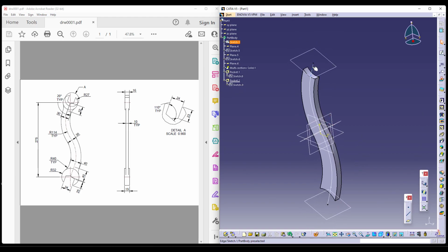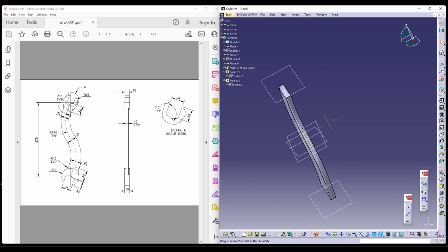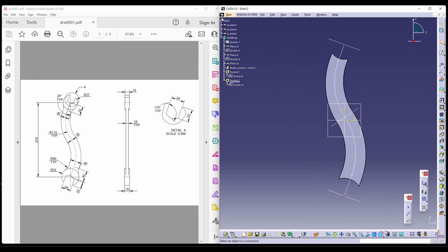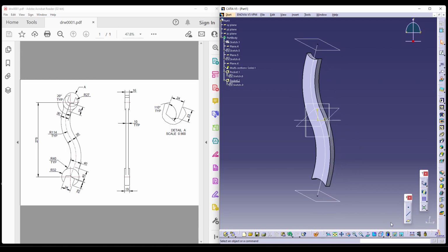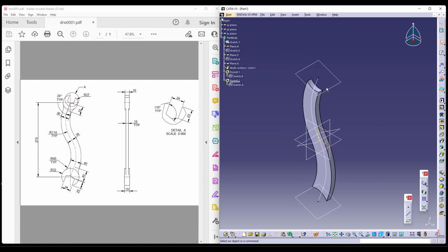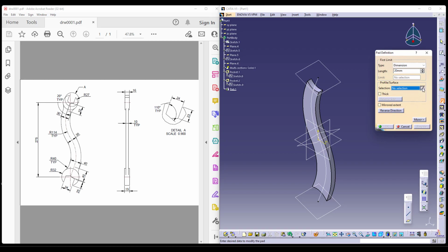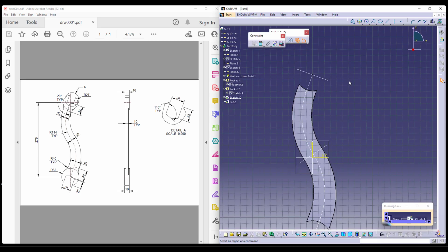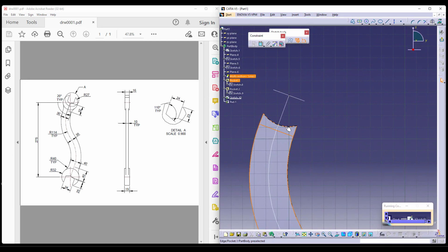Now, let us try to add the material. I can use the center plane because we have given both the sides, I mean, as in symmetry addition of material. We can see that in the right view or in the top view, anywhere you like. So now I'd like to use the center plane. There are different additions of material provided to me. So considering this as a center plane, let us try to add material and do it with respect to the exact shape provided to us.